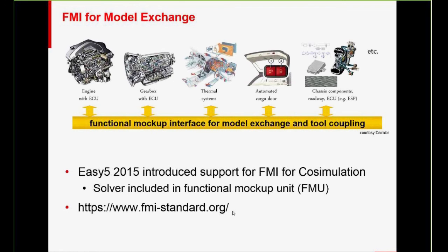If you've never heard of FMI before or need to learn more, the starting point for that is fmi-standard.org. Now, Easy5 2015 introduced support for FMI for co-simulation. For co-simulation, the functional mock-up units include the solver that is specific for that product. So if you export a co-simulation FMU from Easy5, that's going to include all the Easy5 solvers.